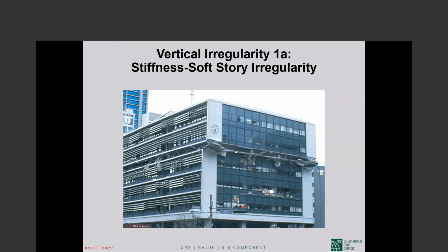So in Japan, quite common is what is called steel reinforced concrete. After the war, everything was scarce, and the Japanese built structural steel shapes into concrete, which were discontinued at some point along the height of the building because steel is expensive, and they felt that they did not need all the stiffness up there,